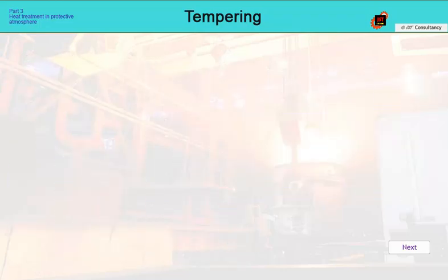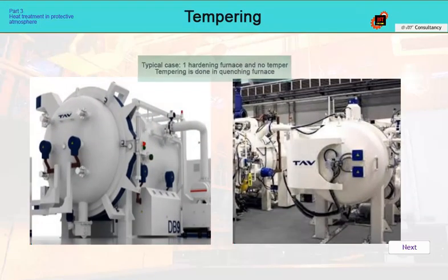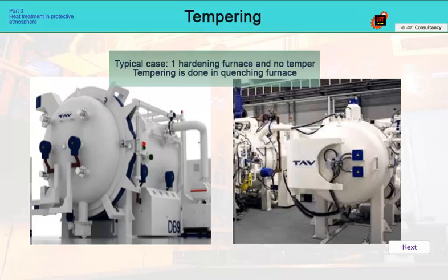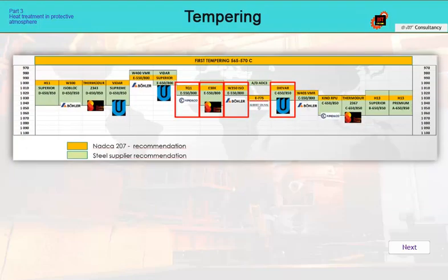If the furnace is validated and released for the production process, we can start tempering. The configuration of the operation is varied, but usually hardening furnaces prevail over tempering furnaces. This is not optimal for the economy of tempering. We will show this on the example of vacuum processing, where the usual requirement today is double or triple tempering. We will process steels for hot work, where there will be more steel grades in one batch, and in addition, a different hardness will be required for each part. For this type of steel, double tempering can be considered standard.